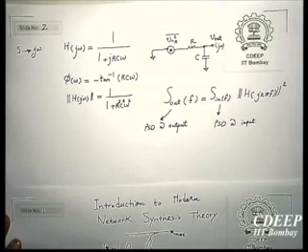In other words, if you have a power spectral density of S in f at the input, power spectral density at the output will be S in multiplied by the square of magnitude of the transfer function. Okay, so we will use this, and then accordingly we can get the power spectral density and accordingly noise at the output.